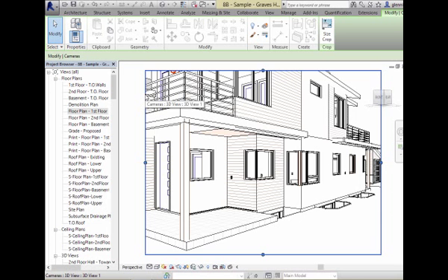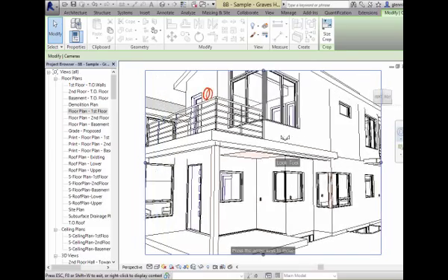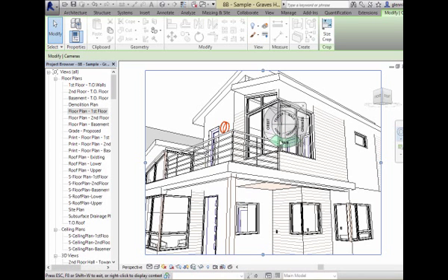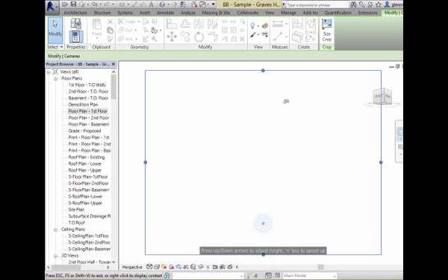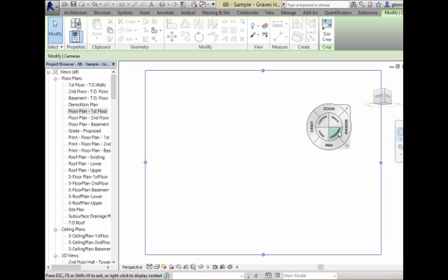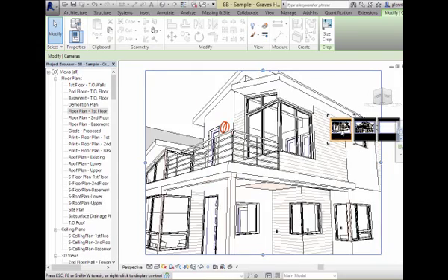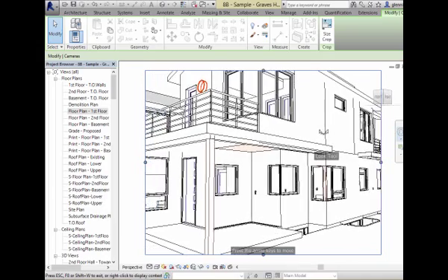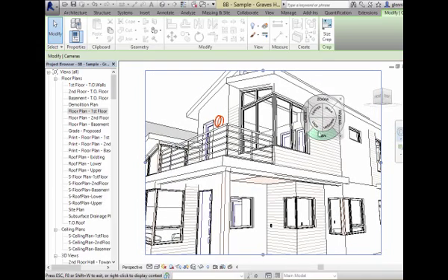That's a starting point. And that camera may not be looking at exactly what you want to be looking at right now. You can always adjust a camera. Under this little steering wheel, you have this look option, which will let you shift it around. That's a little bit dramatic. I may be a little bit close to the house right now, so I can do something like, oops, I walked too far. When I do that, I can rewind to get back to a reasonable spot. Let me try that again. I will look. And what I want to do is actually walk backwards a little bit.